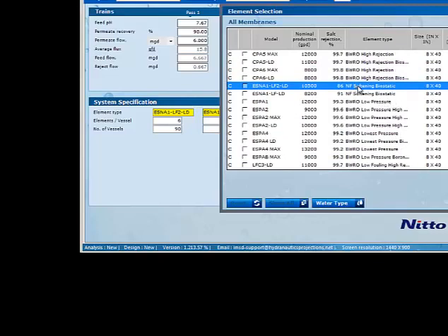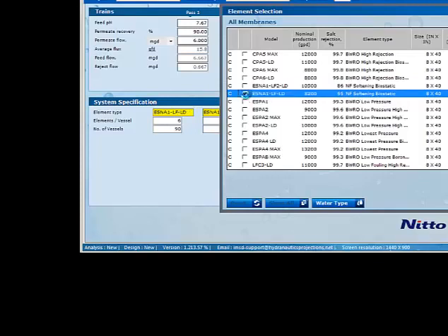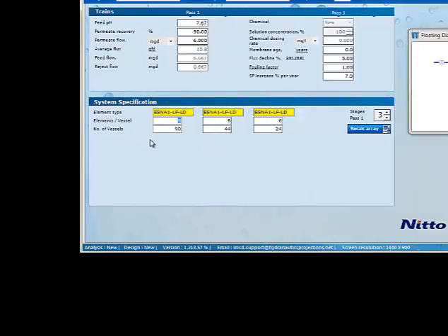So I just went with this nanofiltration softening, and we can either have one or two. Let's choose this one here. Hit OK. And you can see the feed pressures that are there and the permeate TDS concentrations. Hit OK, and then it automatically adjusts and provides a number of arrays that you would need for this. So I'll hit recalc array just to make sure, and lo and behold, we need 90 vessels, 44 for the second pass. They're recommending multiple passes to get that treatment levels down to what we require, and then a third one.